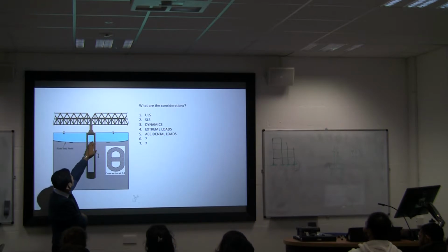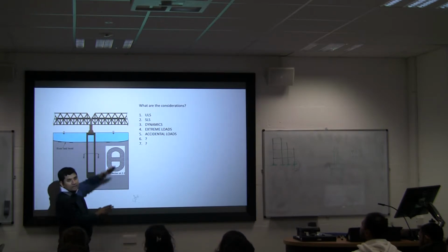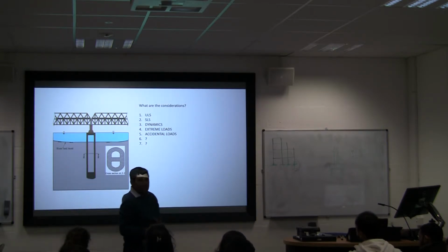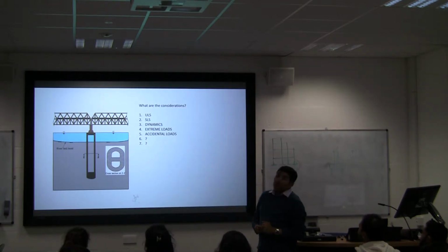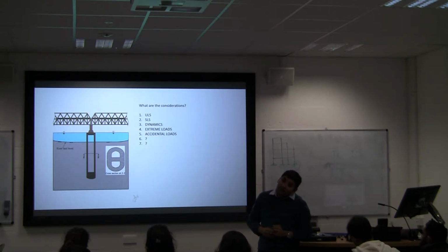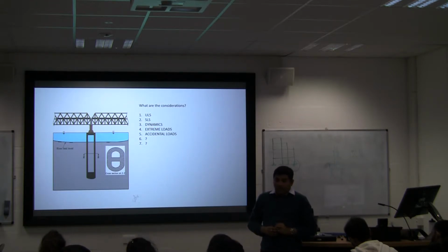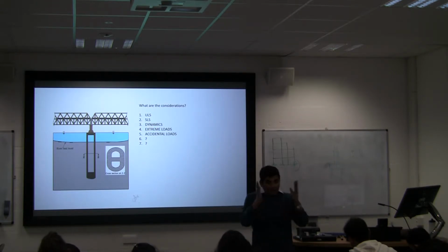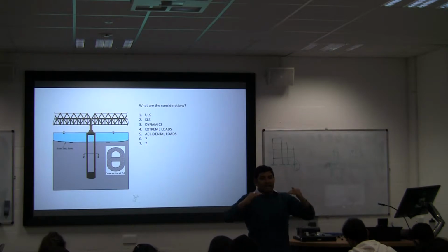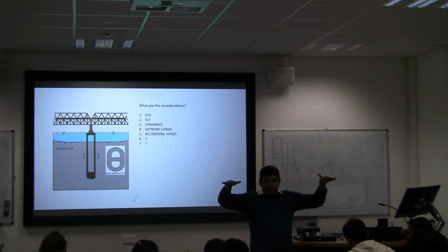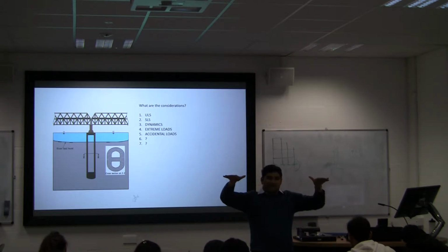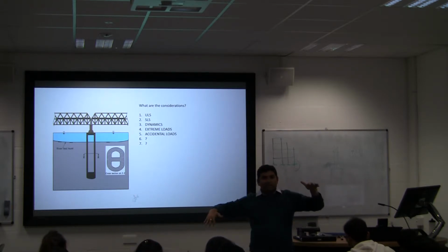If it bends, the deck will follow the bearing. So what you do, you have to estimate the deformation under the extreme load. Once you know the deformation, you can build your pier cap, with a bearing, such that it will not come off the pier cap.